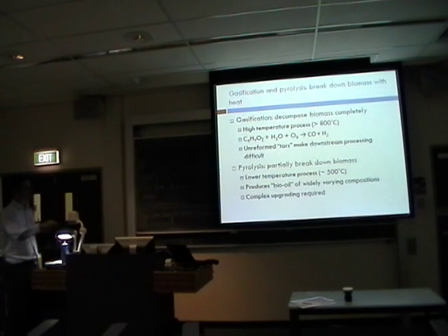And then there's some stuff that it just seems like you can't break down, even going up to as high as 1200 degrees C thermally, and it gums up the works downstream in the process. Right? There's another potential problem with gasification. Pyrolysis, you try to partially break it down. I guess maybe another thing I don't like about gasification is you already have some nice 6 and 5 carbon units that are strung together in pretty intriguing ways. You just have also high oxygen content. And it would be nice not to break it all the way down and waste all the work that nature has done before you try to reassemble it to make hydrocarbon products. Okay, so there's some inherent efficiency disadvantages with doing it this way.